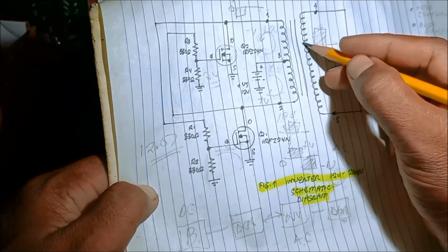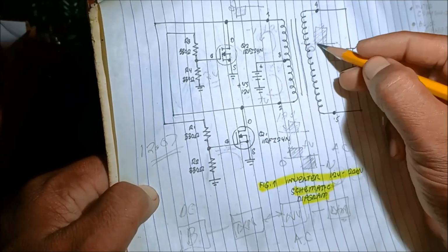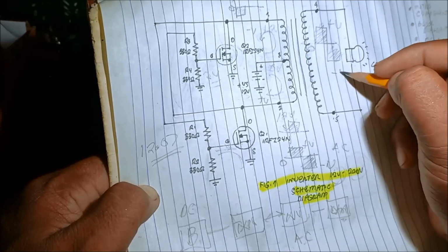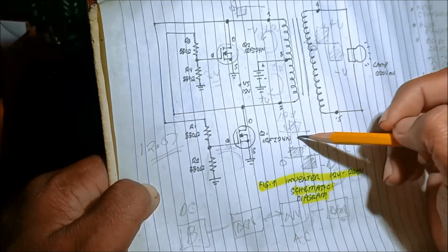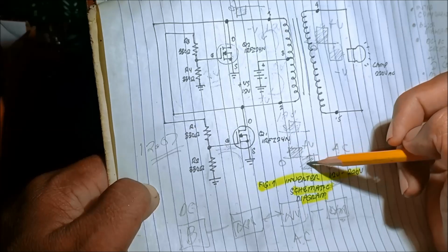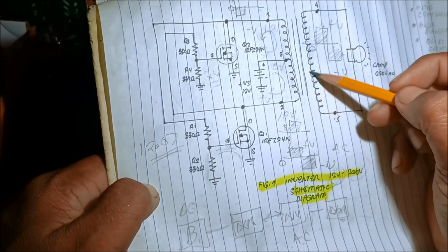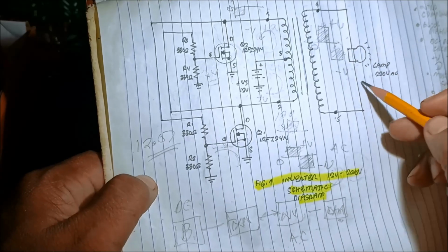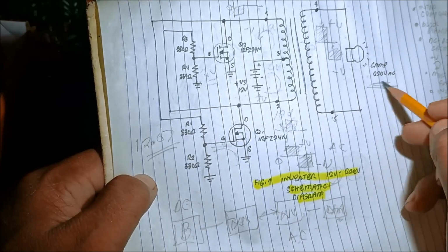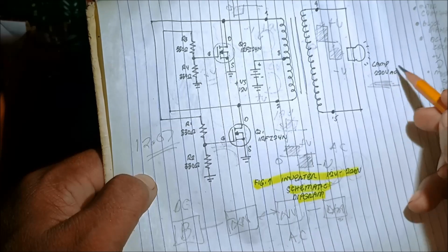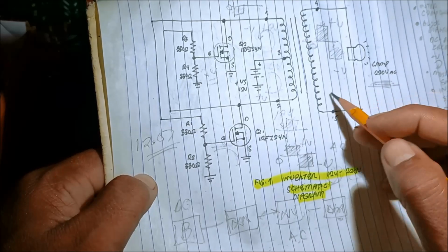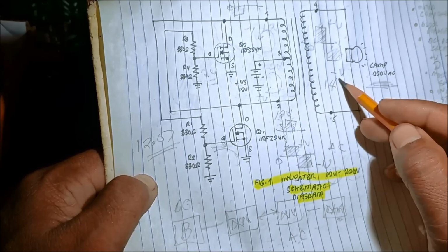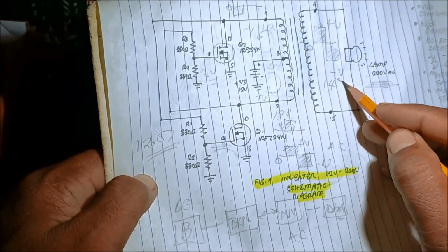This is in a zero or reference ground, and then there is a positive voltage and negative voltage. So from a small alternating current of square wave, due to the induction, we now have a much bigger one, which is capable of turning on this LED lamp. It will turn on the LED lamp. But the voltage developed is around 147 volts